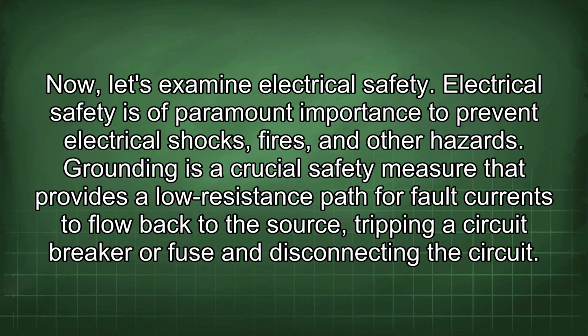Now let's examine electrical safety. Electrical safety is of paramount importance to prevent electrical shocks, fires, and other hazards. Grounding is a crucial safety measure that provides a low resistance path for fault currents to flow back to the source, tripping a circuit breaker or fuse and disconnecting the circuit.